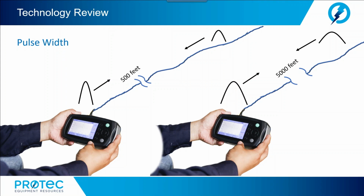Now let's talk a little bit about pulse width. Does it matter if the event that we are trying to find is very close to the TDR or very far away from the TDR? Well, it sure does. We can look along the entire distance of a very long cable by varying the power, the width, of the pulse that the TDR sends out. This is the amount of time that the transmitter is turned on. We set the pulse width.